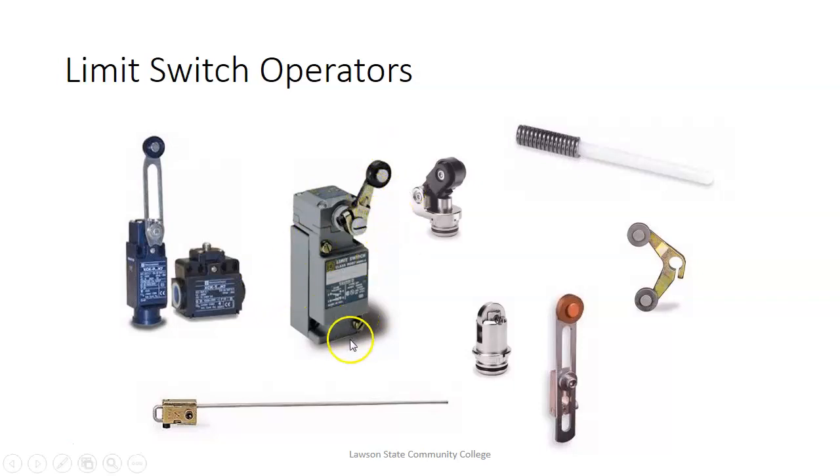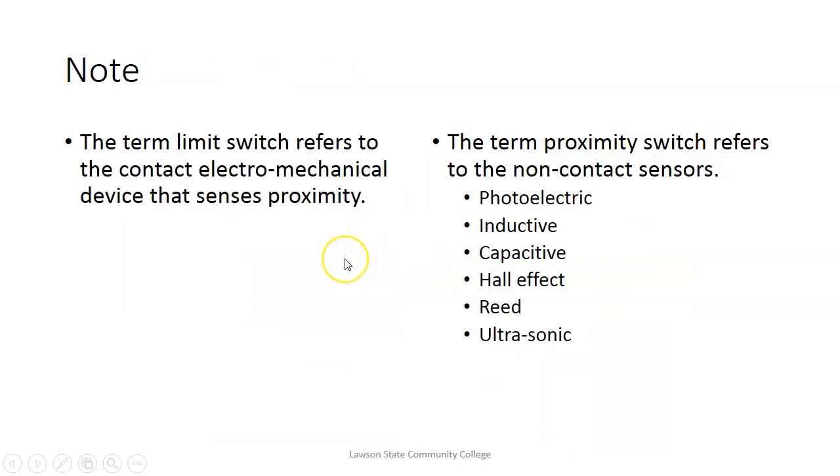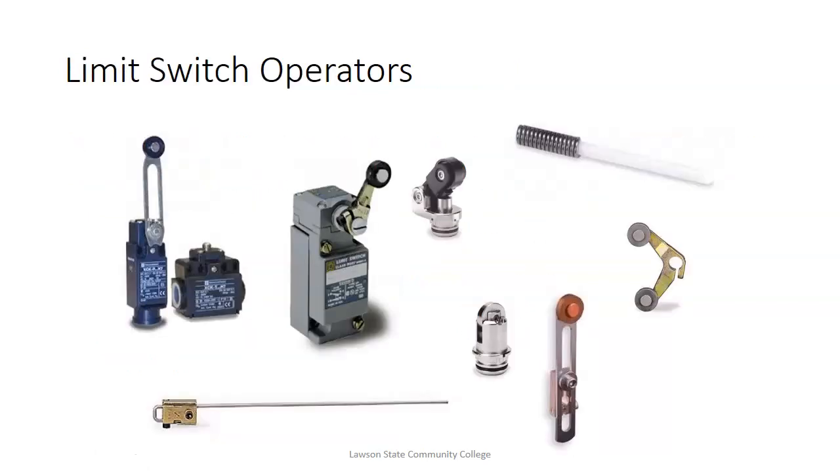Also, when they wire it up, they'll remove these covers. These covers have a nice rubber seal in them to seal them up. It's down here where the wire conductors come in from the bottom. It's got an assembly that clamps the wire in, with rubber on there that allows it to seal up. What'll happen is somebody will take off the cover and not screw it back on, or leave it off completely. Then out in industry you get all kinds of goop in there, or they don't seal up the bottom correctly, so corrosion gets inside of them, or they try to get too much current out of them.